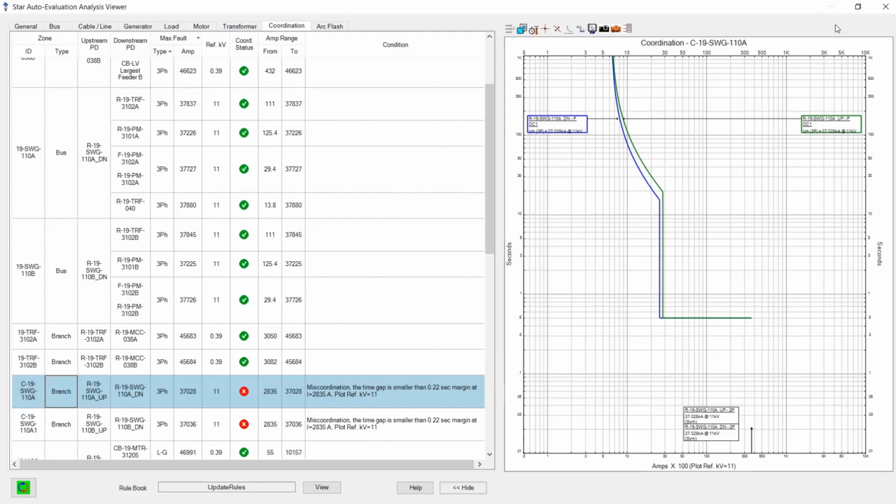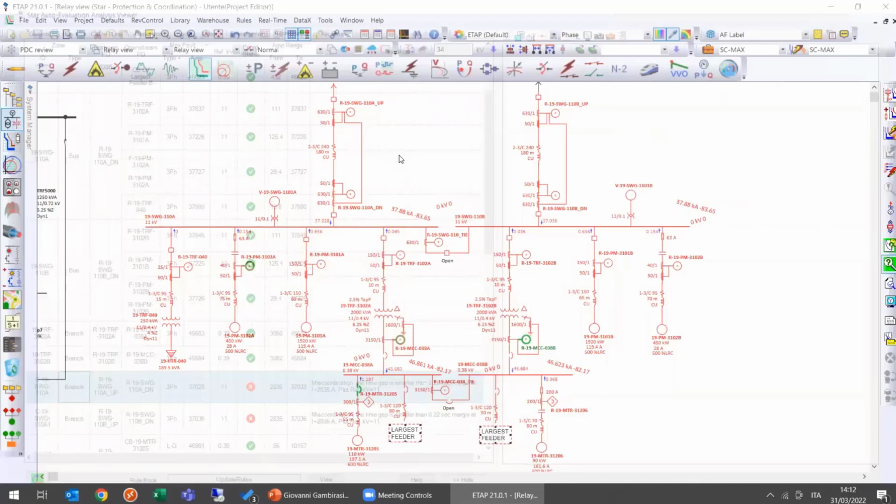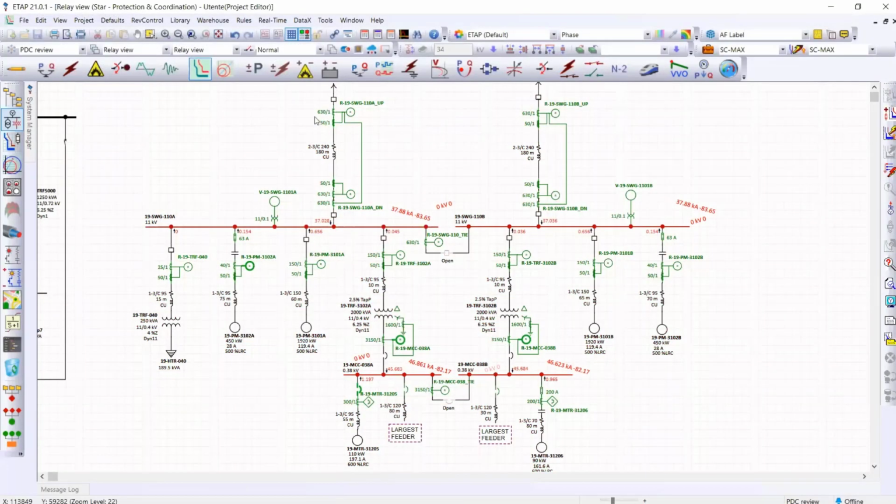So especially it is going to work on this area, but we know it, and we know that for the line protection, we can even not have coordination between primary and secondary side, because if the fault is in the cable, we have differential protection. So in any case, we can delay the fault coordinately and selectively, and anyway, it's a feeder connection, so the trip of upstream and downstream will be reflecting the same element.